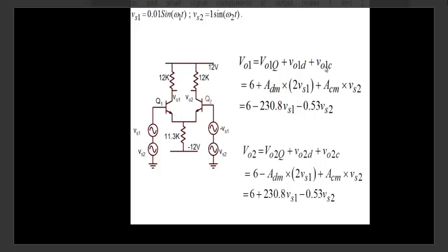And you calculate what is the common mode current. Okay, so as I said, everything is now two parts here. You should know what is the differential mode circuit, where this becomes ground, and what is the common mode circuit, where this becomes 2RE. On that basis, you can calculate what is the base current here and what is the net value of base current at this particular point.